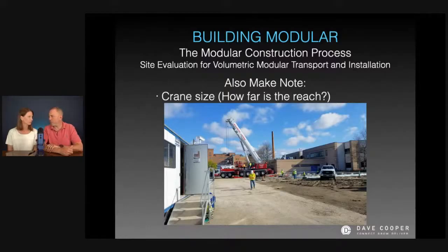So if you can't get close enough to the single family, let's say you're using a Superior Walls foundation and you have to leave it exposed, with the dirt on the outside and not backfilled, then you can find yourself needing a larger crane. In a case like this, it was very well thought out. That crane set the first 8 modules that first day, and then they set the other 8 the next day.